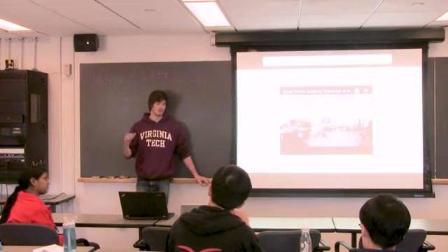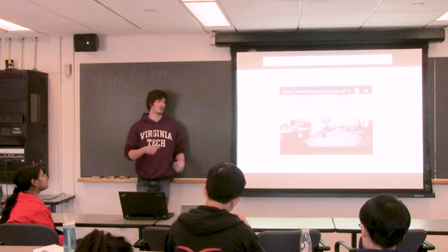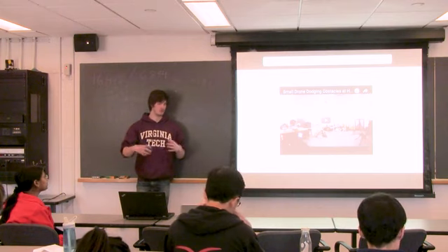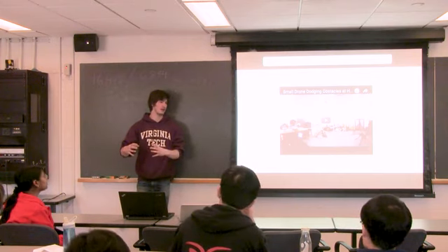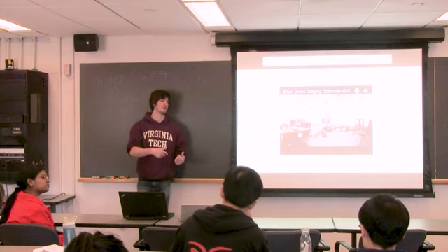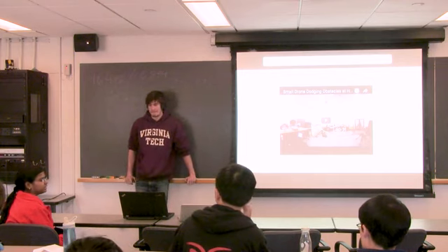So a lot of people compute the library offline for a trajectory and plan using that. But here, you compute your trajectory and the funnel around it offline, and then you search through the funnel library. You don't search through trajectories and then try to fit a funnel around one. You just search through the funnels directly. If you don't have a very good library, then you might not get a very good trajectory.